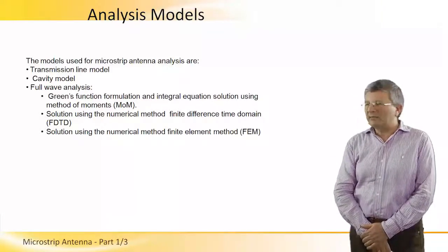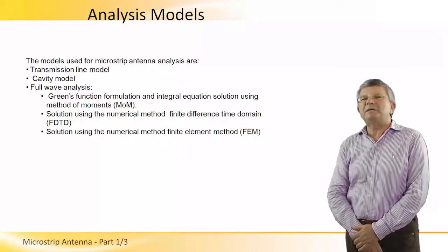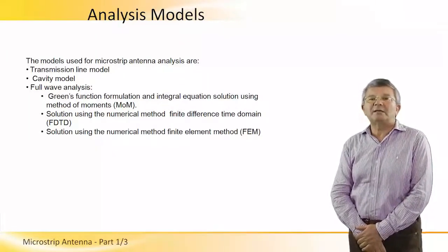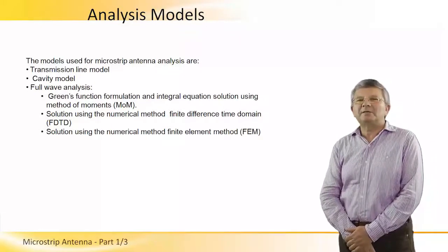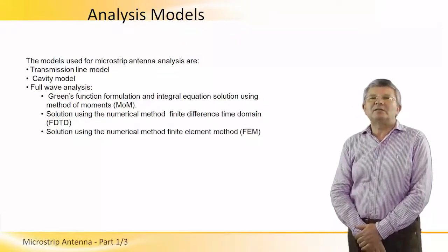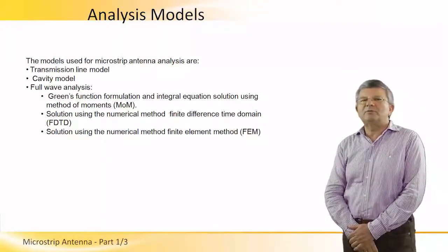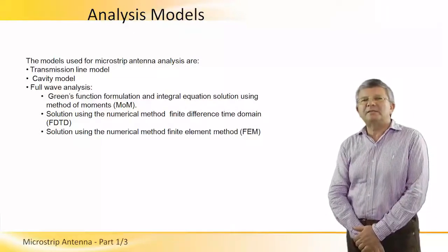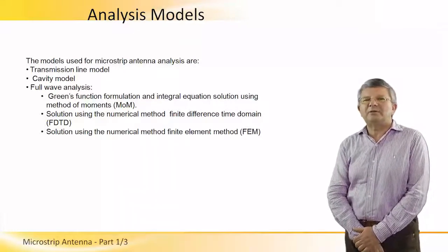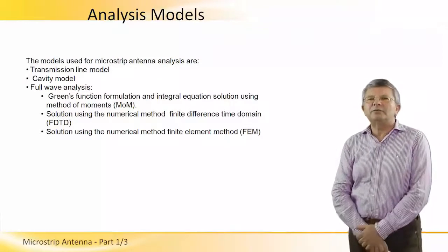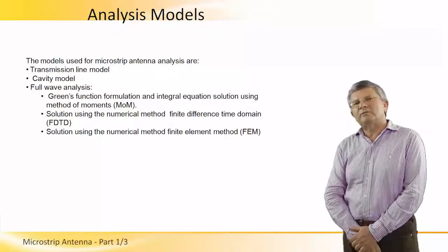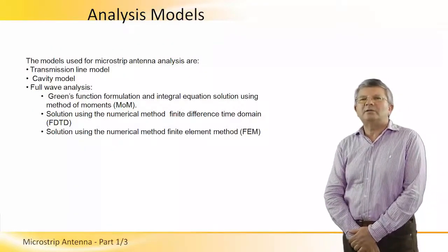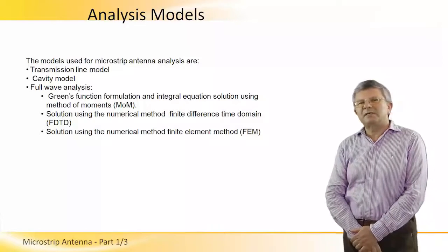All three methods have today been implemented, and one can find commercialized software which implements the three approaches, such that, for instance, the integral equation method can be found in a software called IE3D by Zeland. The FDTD can be found in a software called Microwave Studio from CST, and the finite element method can be found in the software HFSS by ANSYS.